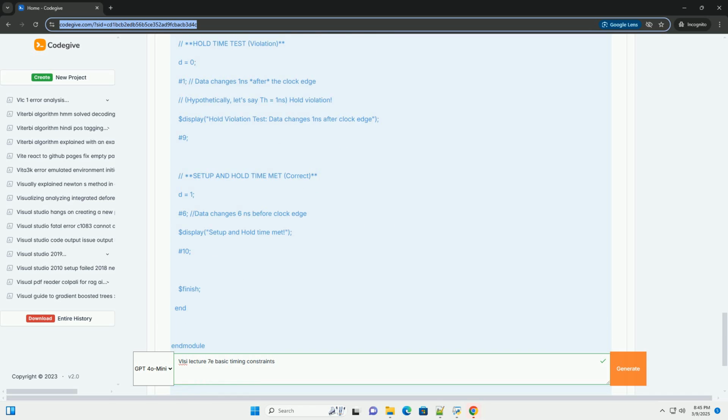Intuition: After you press the camera's shutter, you need to keep the camera still for a brief moment to avoid blurring the photo. Similarly, the data signal needs to remain stable for a short period after the clock edge arrives, ensuring the flip-flop correctly latches the data. Violation: If the data changes too soon after the active clock edge, i.e., if the hold time requirement is not met, the flip-flop might incorrectly latch the old data, or again, it might enter a metastable state.